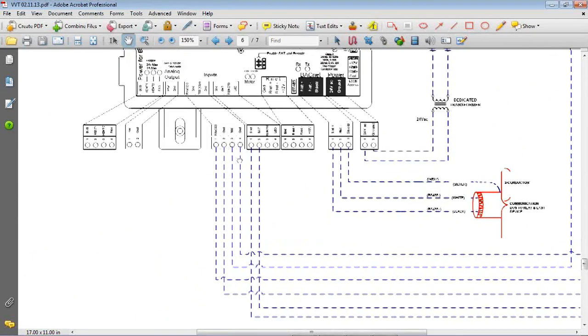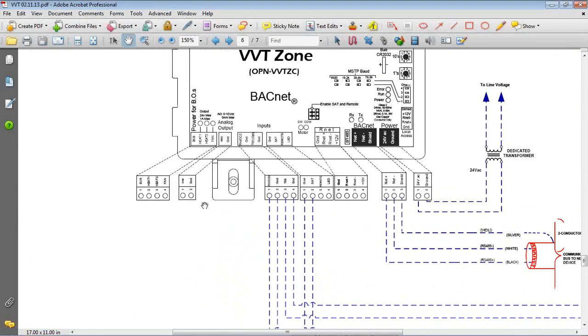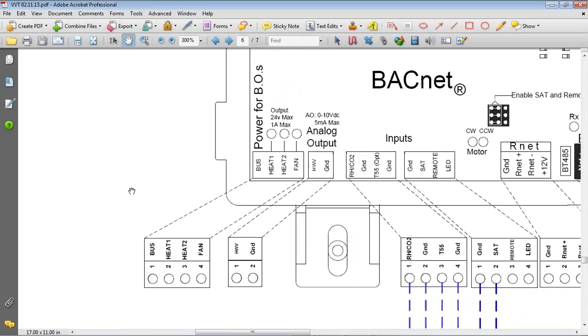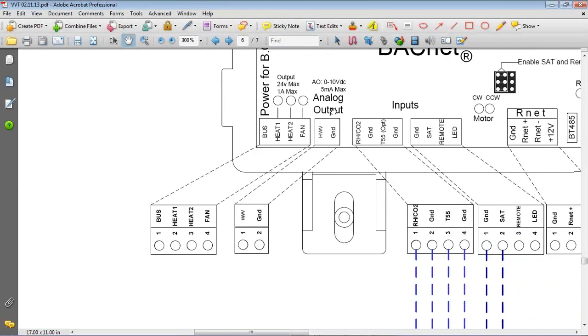So moving on here, the last two plugs we have on here are actual outputs from the controller, and these are for reheat or slaving an actuator. If we zoom in a little bit here, we have one analog output that is labeled as hot water valve, and this would be for modulating a hot water valve or for an SCR type control or a modulating electric heat control.